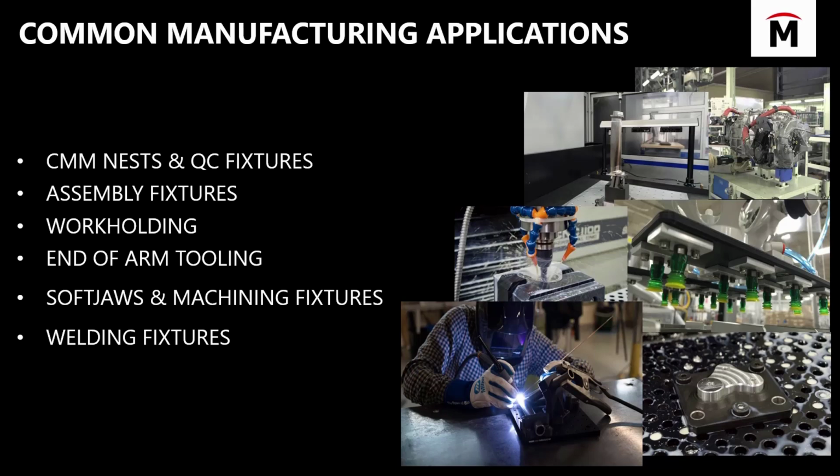Custom welding fixtures are actually a great application, believe it or not, since our material is heat tolerant up to 150 C. You can design and print your fixture to hold your complex angles for welding. You can even print cut fixtures to miter the complex joints. I have a customer that actually does this. So they cut the form. In other words, the little piece that they slide over the pipe that they draw the miter on, then they cut the part, and then they have a printed fixture that holds all those things together.